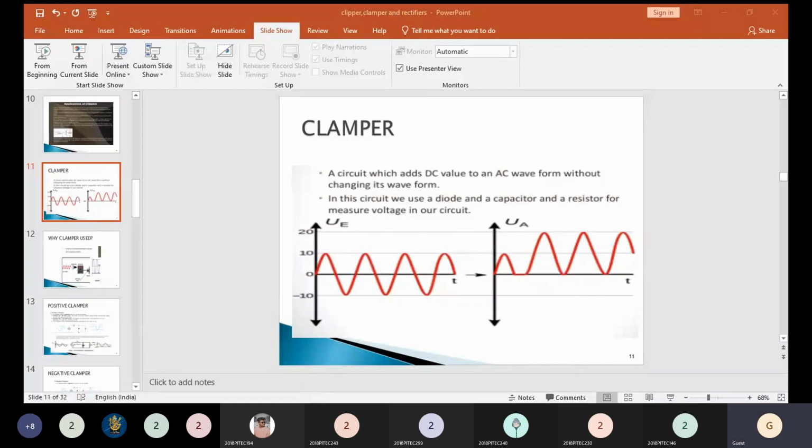For supply 1, that is A, power supply A delivers 10 voltage, with a ripple of 0.5. VDC value is 10. Calculating in terms of percentage, it is 5%. Okay. Next for supply B, the same method, same steps, same formula. You are going to compare both values, power supply A and power supply B, and finally decide which is the better power supply.